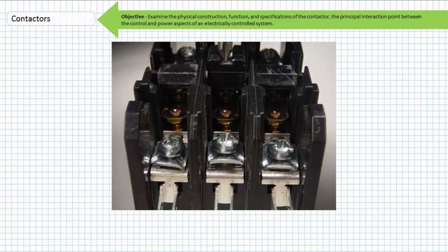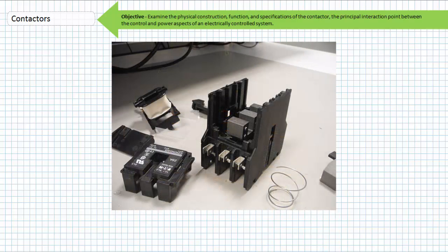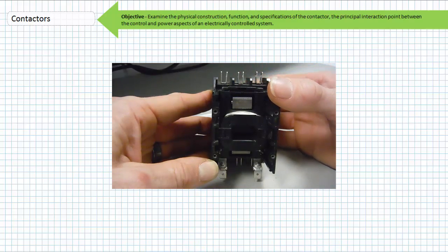Dedicated purpose contactors are used for applications that don't require holding contacts or feedback about contactor status, as we'll learn in later lectures. Here's this same contactor disassembled. We find the linear actuation mechanism similar to our first contactor. When de-energized, the return spring keeps the armature retracted. When energized, the armature is pulled into the coil to close the contacts attached to the contact carrier. When de-energized, the return spring opens the contacts.